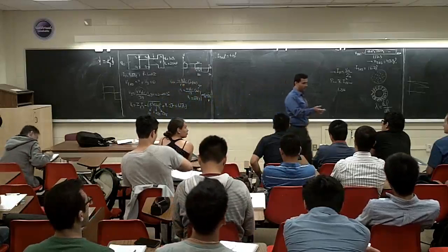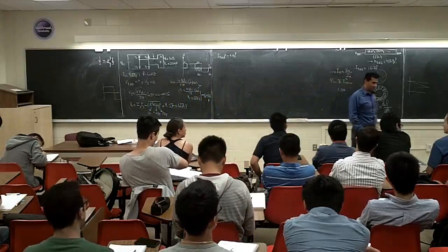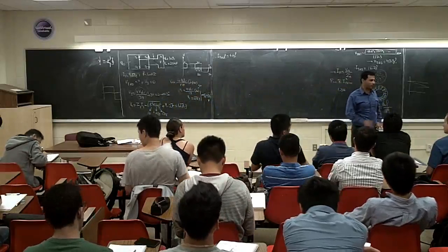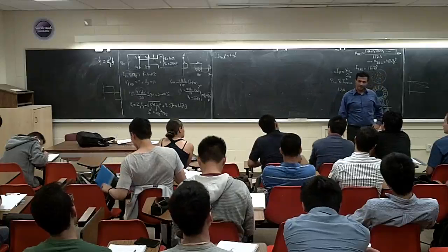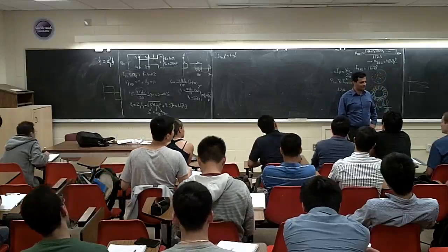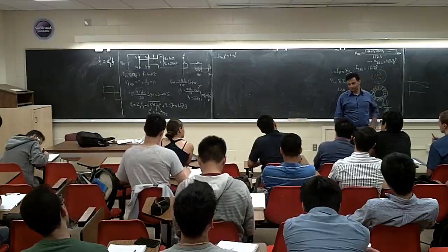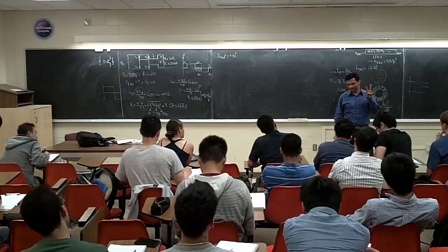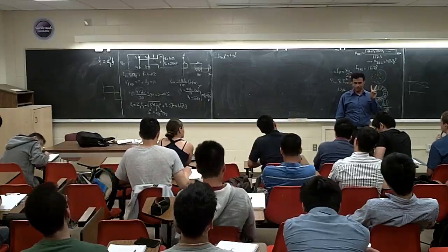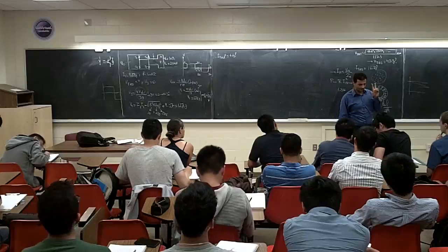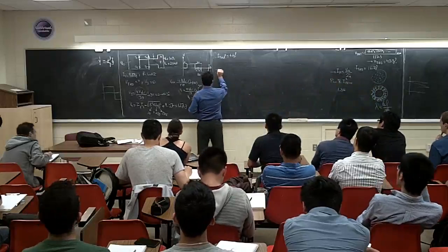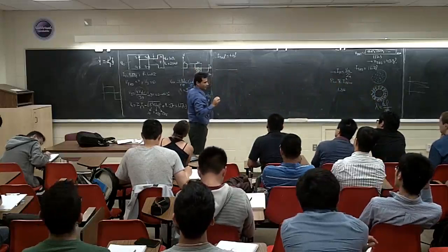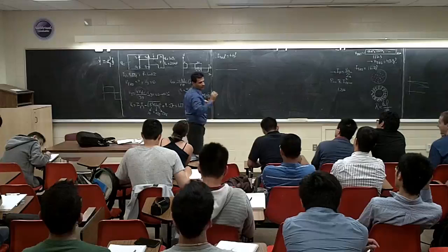No, I'm saying, I don't know what the number is, but let's say for eliminating the fifth harmonic, you need a 20 degree, for example. How about if I have an alpha and beta? So there are two, I want to get rid of two, right? I should have two parameters to control, right? Now, this is a little bit more advanced harmonic elimination. If you are going to do that one, you need to have chopping. So I'm going to give you the homework.